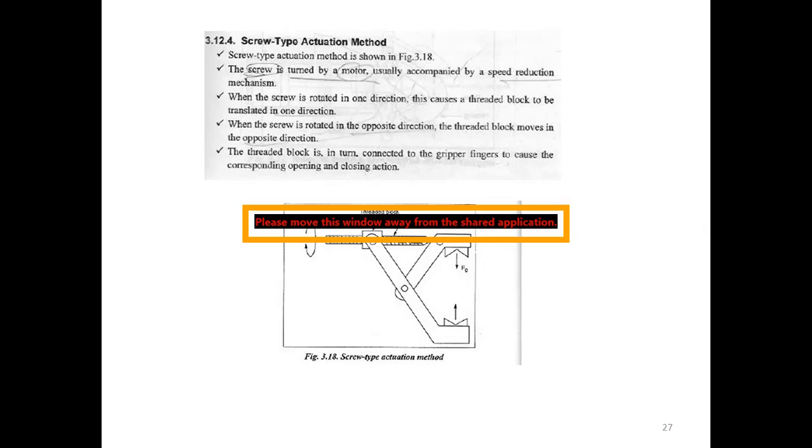Lead screw actuators have a compact form, along with a rotating nut inside the cylinder. The motion is constrained within the cylinder, and it is the nut that moves. The electric screw actuators are self-locking and have a minimum number of moving parts around them. The lead screw is a kind of mechanical linear actuator which is able to convert rotational motion into linear motion.